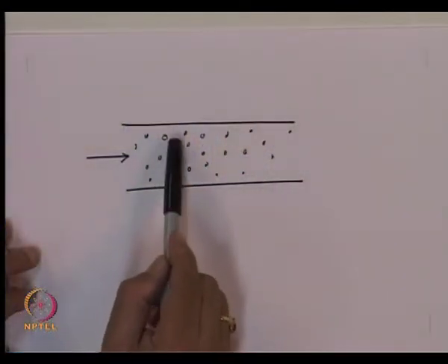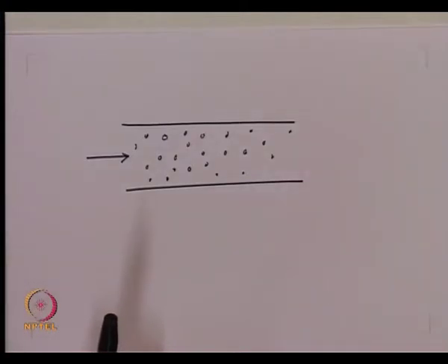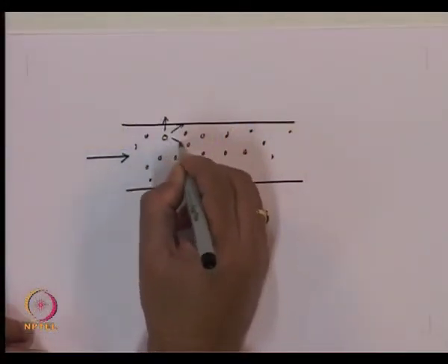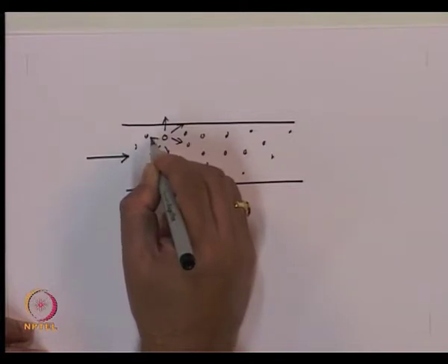This phenomenon is very similar to when a microwave signal tries to propagate in the atmosphere, and if there are raindrops, that microwave signal gets scattered by the raindrops. Precisely the same phenomenon which you see here, that these micro centers have sizes smaller than the wavelength. So you see scattering of light taking place because of this, and that scattering is what is called the Rayleigh scattering. So essentially, due to this, a very tiny fraction of light gets scattered into all directions, everywhere.